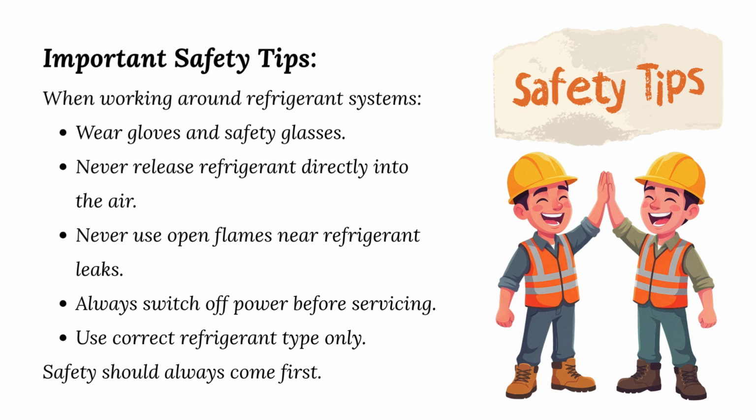Important safety tips. When working around refrigerant systems, wear gloves and safety glasses. Never release refrigerant directly into the air. Never use open flames near refrigerant leaks. Always switch off power before servicing. Use correct refrigerant type only. Safety should always come first.